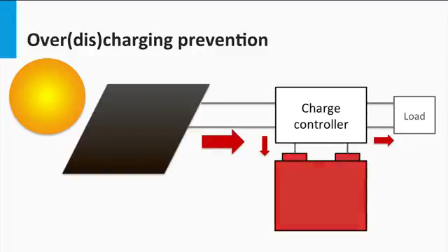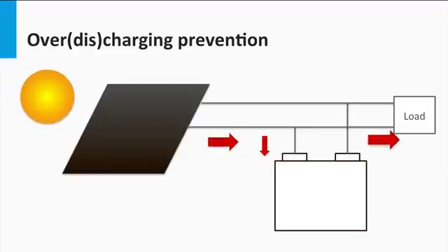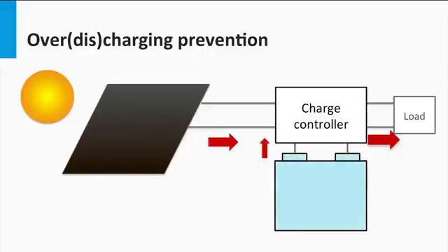The charge controller here plays a vital role by cutting off the PV power from overcharging the battery. Similarly, in severe winters, when low irradiance causes the load demand to be more than the supply power, the battery is heavily drawn. The battery under such conditions tends to be over-discharged, which weighs strongly on the battery life as discussed in the previous block. The charge controller under such a case prevents over-discharge by disconnecting the battery from the load.